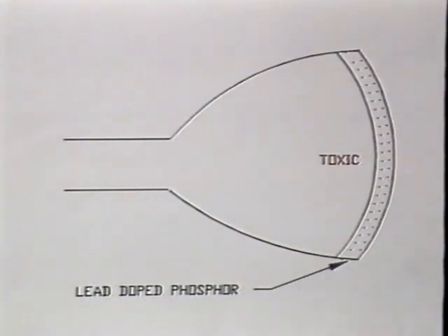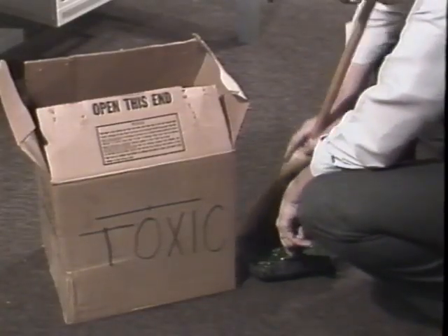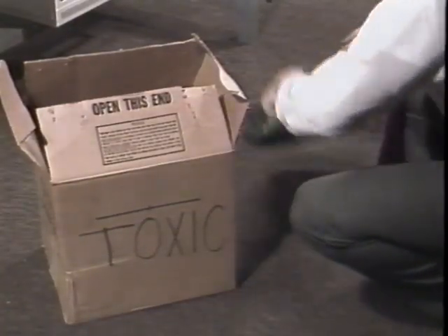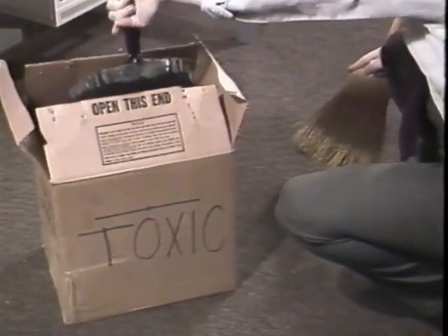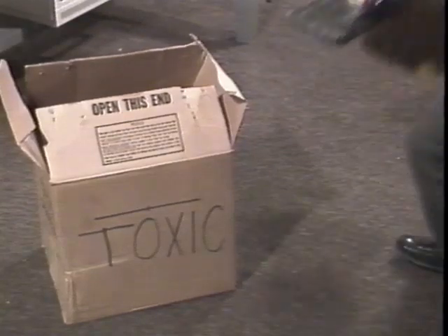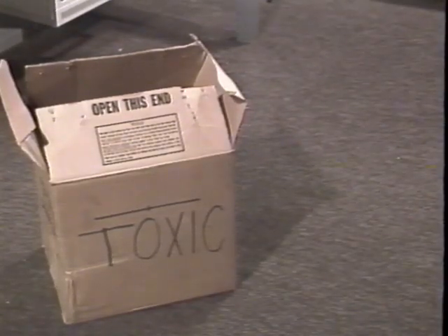The lead and possibly also the phosphor itself are toxic. If a CRT were to break, the lead-coated glass could poison anyone that it cut or contaminate the environment. For this reason, it is illegal in some states to put a CRT in the trash. Check local regulations before throwing them away, and be extremely careful if cleaning up a broken tube.